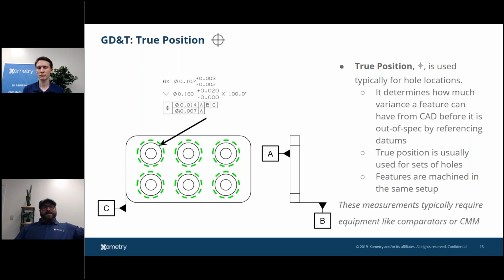So just take into consideration, you'd be surprised how many people put on a 1 thou true position, and that's not really reasonable. Those CNC machining centers have more error than that. So just consider your tolerancing when you're doing it. Obviously, tighter tolerances make the price go way up because it requires more setup, it requires more stringent checking of the part in between actually running tools, and just adds time overall. And it adds risk to that too.